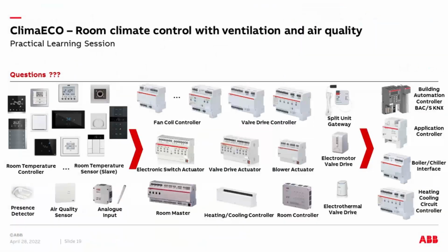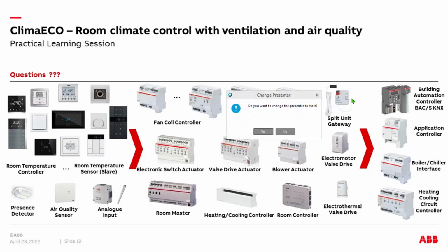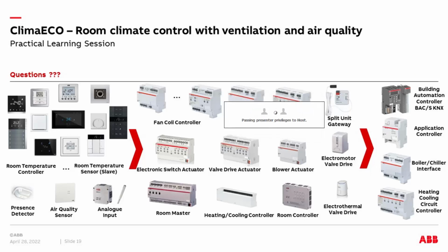Thank you, Jürgen, for this mainly practical demonstration. I think it's not a miracle what we are doing here. It's standard assignment of group addresses. Okay, we have 3 controllers in our components. A bit tricky, or let me say a bit more powerful, is this evaluation of the highest control value, as we have seen, that you always control according to the most critical situation, either relative humidity or CO2 concentration.